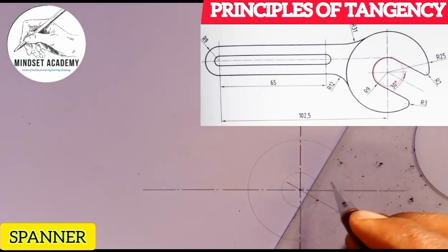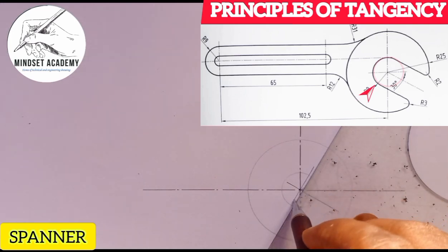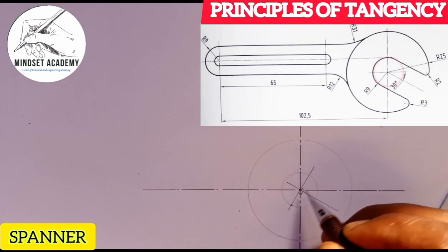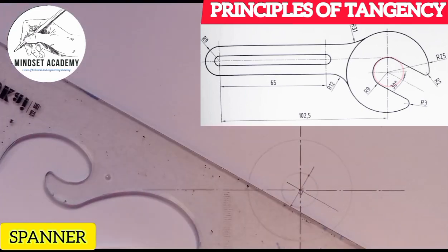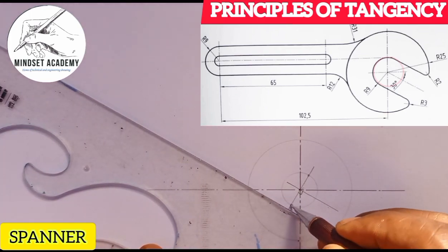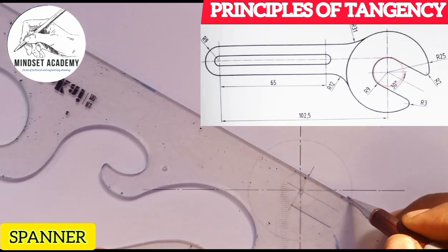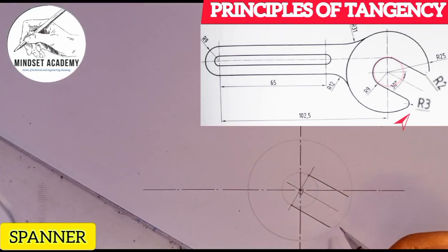So I'll do the same thing here too. This 30 and 60 are forming an angle of 90. Where it meets here and here, that is where I'm going to draw my line that is parallel to this line, that is at 30 degrees. So I'll place it here and draw an arc this way. I'll place it here and draw another arc this way. But the arc here is radius 2, very small.